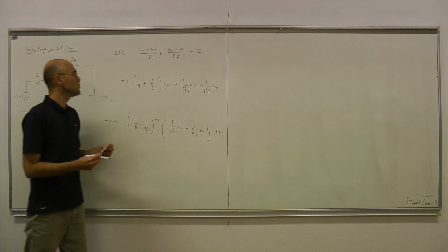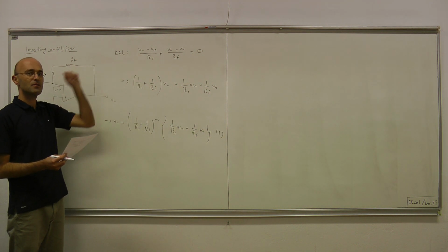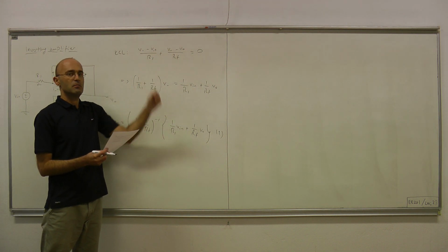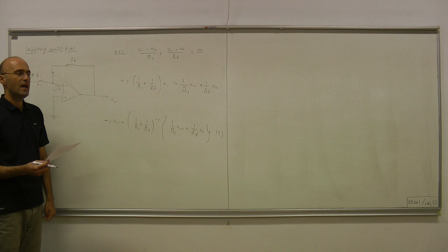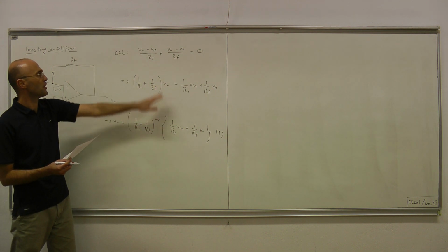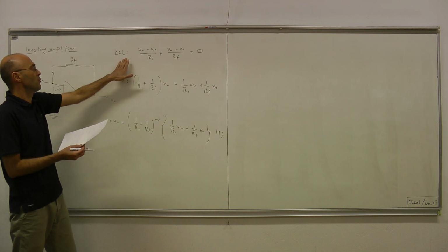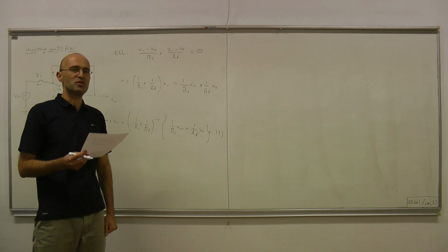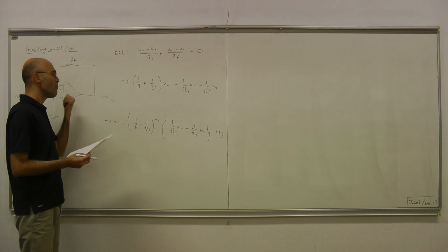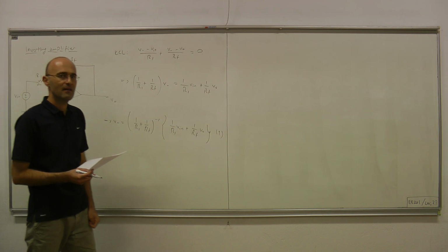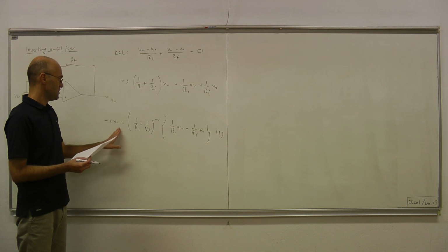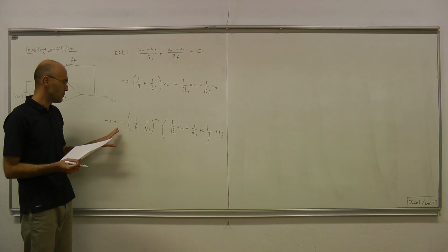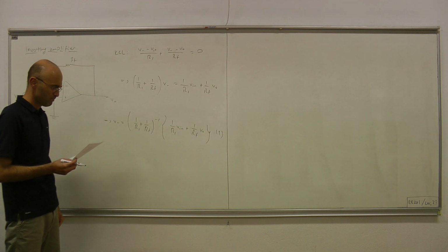So what we did is we obtained V minus in terms of the output and input voltages. Note that when writing this equation, which is basically just one equation, KCL, we didn't have to make any assumption on what region the op-amp is operating in. Therefore, this relation must hold at all regions. That's a region-free operation.